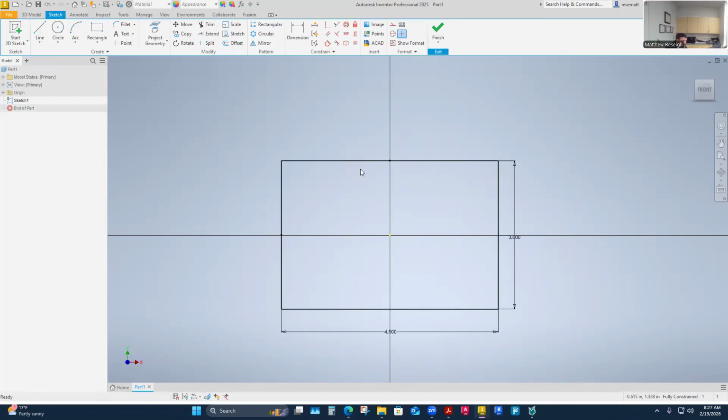And I'm going to go ahead and do all the holes in this. So I'll just draw these as circles. So I think I will put one circle in here that is 0.5625 in diameter. That's 9/16. And then I will dimension one of these. I think I'll actually dimension this one maybe and pattern this. It wouldn't really matter. I'm just looking at what dimensions I have to work with for my drawing.